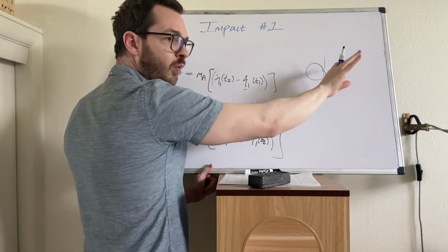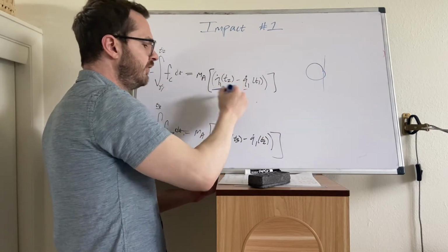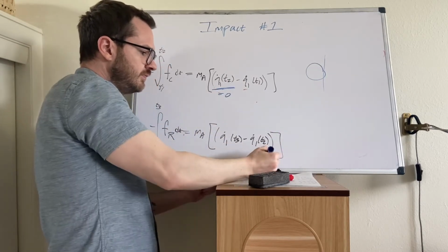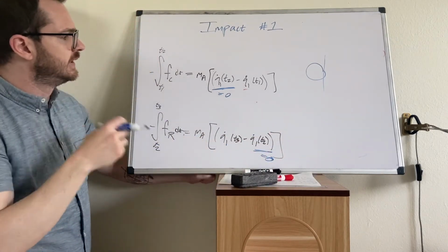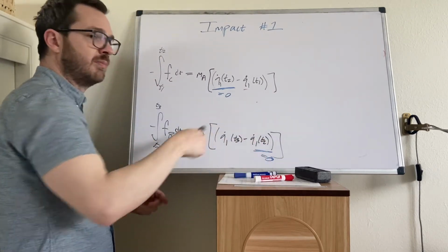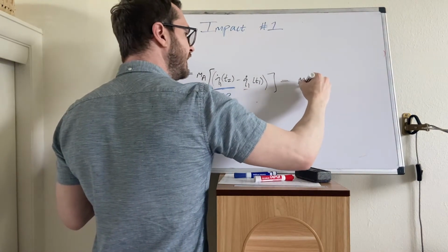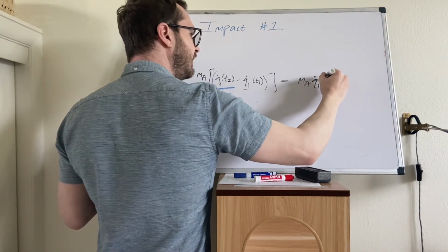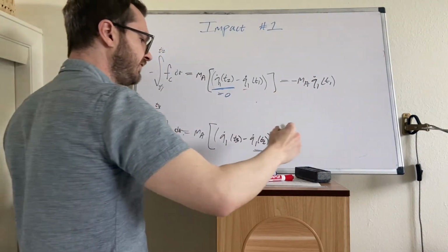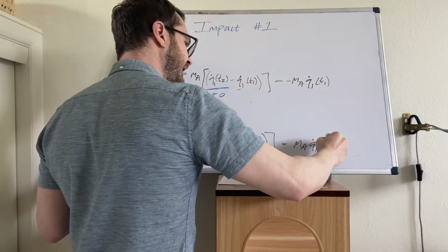That means it hits the wall and it comes to a stop, and then it's going to start coming back out. So at time 2, these values are actually 0 at the maximum compression. Okay, that means we can simplify a little bit more. Equation number 1, I'm going to leave the left side as is, and this is going to equal ma q1 dot at time number 1, and it is negative. The last equation, this is ma q1 dot at time 3.